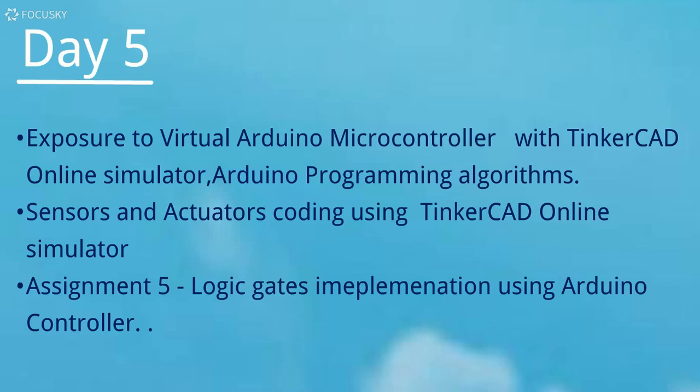And in that one, you have sensors, you have actuators, and we're going to teach you how to do the coding for any kind of actuators or any kind of sensors by using the Tinkercad online simulator. And by using this particular Arduino controller, with the push buttons and a couple of sensors, you can do the logic gate implementation. That is the day 5 content.